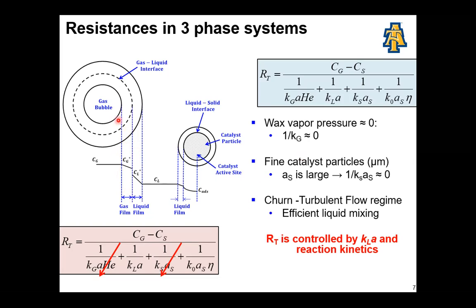Yeah. So again, I'm saying the molecule will have to diffuse from the gas bubble through the gas-liquid interface. You see the blue writing here, gas-liquid interface, at the top. Through the gas-liquid interface, it will get into the liquid bulk, which is the bulk of the liquid. And then it has to move through the liquid-solid interface. You see it at the top here, written above the circle. Liquid-solid interface, and then finally reach the catalyst particle for the reaction to happen. Okay? So if we write the overall, sorry, you can move on to the blue equation right here.